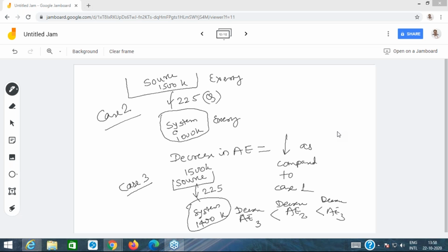So I hope you have understood that if you transfer the heat without any heat loss, I'm underlining this, without any heat loss, even if you are having zero heat loss, but you are transferring the heat through a finite temperature difference, the quantity of the heat remains the same, but the quality of the heat degrades. The available energy decreases, the exergy decreases, and this exergy destruction, this decrease in the unavailable energy, is because of irreversibility.